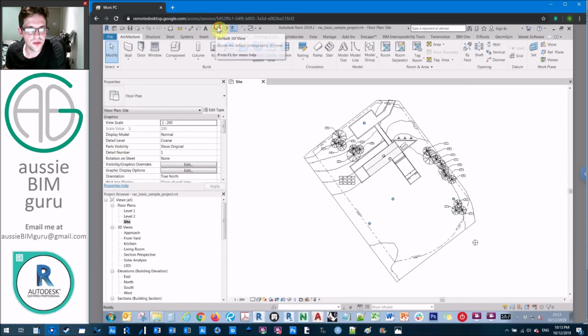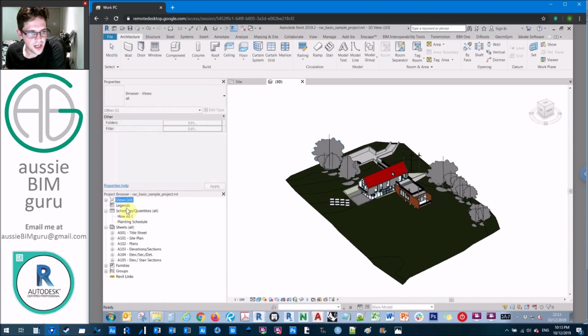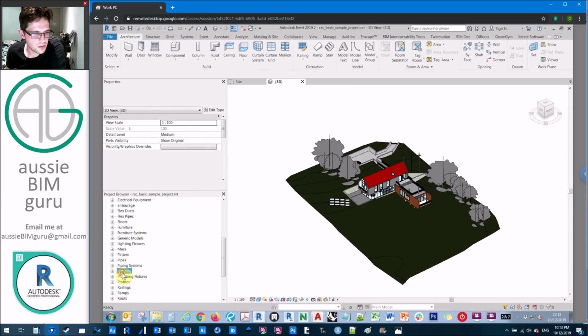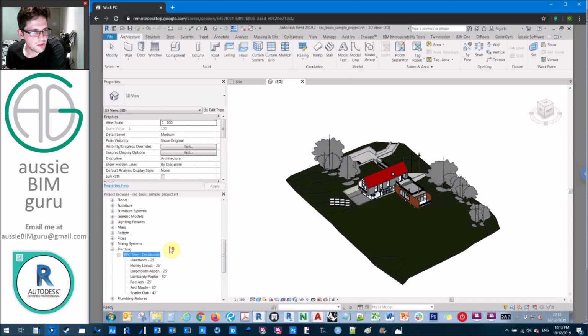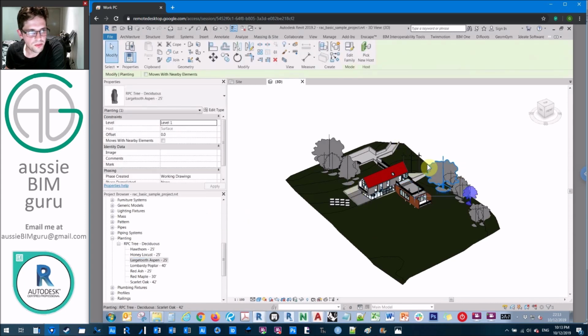And then what we're going to do is delete our trees. Before I delete them, I'll just draw emphasis to the fact that they have different types for different tree species. So typically when CAD blocks are created from a Revit export, they'll be named based on the family type and family. So you can see we've got different species. So these aren't just all the same tree. So we're going to want to source the block information to place the right family instance per block location.